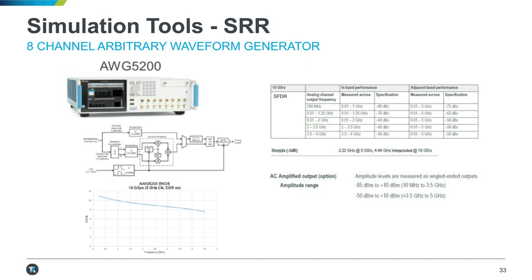It's very good for long range radar, a radar that has a chirp of probably less than a gigahertz. So this would be a good tool for generating 600 megahertz, 500 megahertz, 800 megahertz chirps on each one of its 8 channels to emulate different targets.